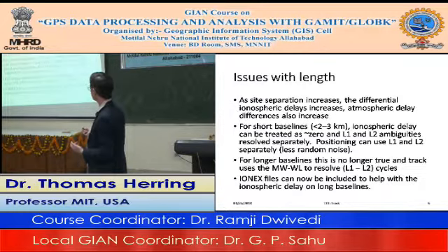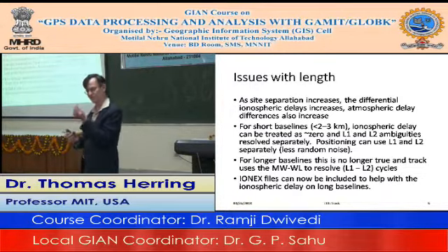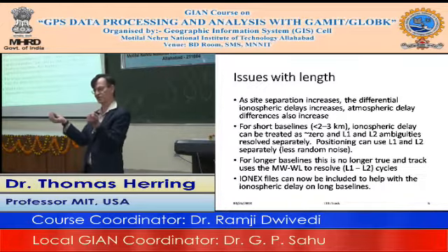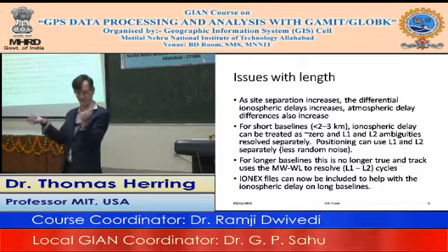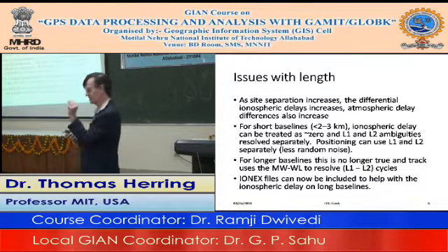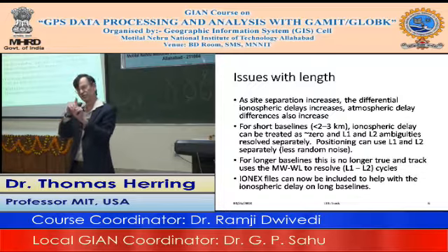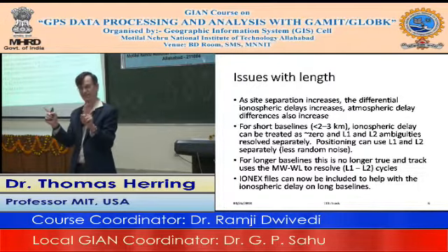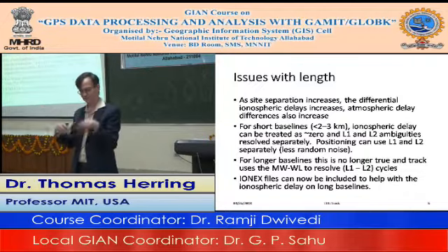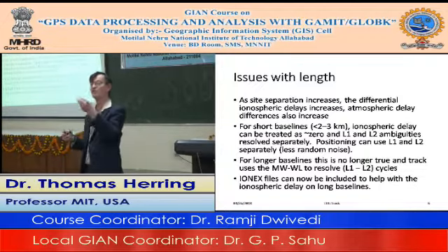Now, the increase in the ionospheric delay itself is in theory not a massive problem because we're doing dual frequency ionospheric correction. So we can get the correction correct easily enough on the long baselines. But where it makes a difference is when you want to look at the L1, L2 difference in ambiguities. If you remember, we had that lecture where we talked about those different combinations of data.